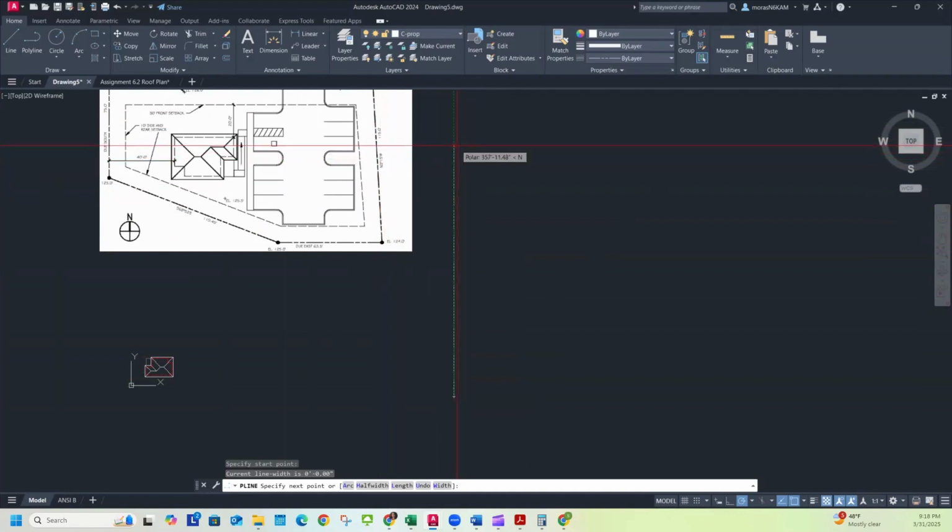The syntax for that would be at the distance, so 115 feet, and then I'm going to do the angle sign, N, 3, D for degrees, then 15 and apostrophe for minutes, and then W for west. So look down here at my command line, and that's what I have before I press enter.